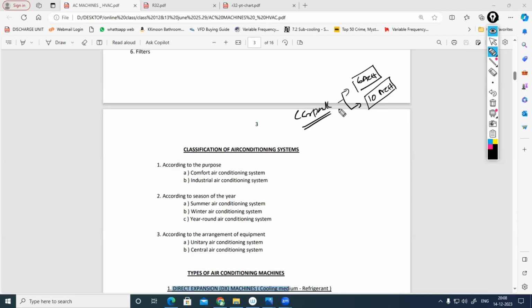I will explain. To maintain the indoor air quality as per ASHRAE, we have certain ppm ranges of carbon dioxide. So when we are designing DCV, called demand control ventilation, it is normally not mandatory to work your ventilation machine continuously. Whenever it is in demand, at that time only it has to work. As I told in the HAP classes, after finishing the machine, I will go back to the HAP session.